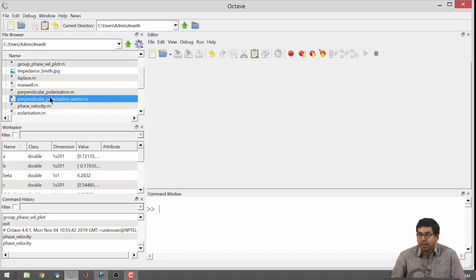For the rectangular waveguide, you may need to write some 3-dimensional Maxwell equation code that will have Ex, Ey, Ez, Hx, Hy, Hz, and you will have a solution in all the 3D space and 1D time. Then you have to take a slice and solve. It's too hectic. So, in this case what we are doing is we are reducing the problem from 3